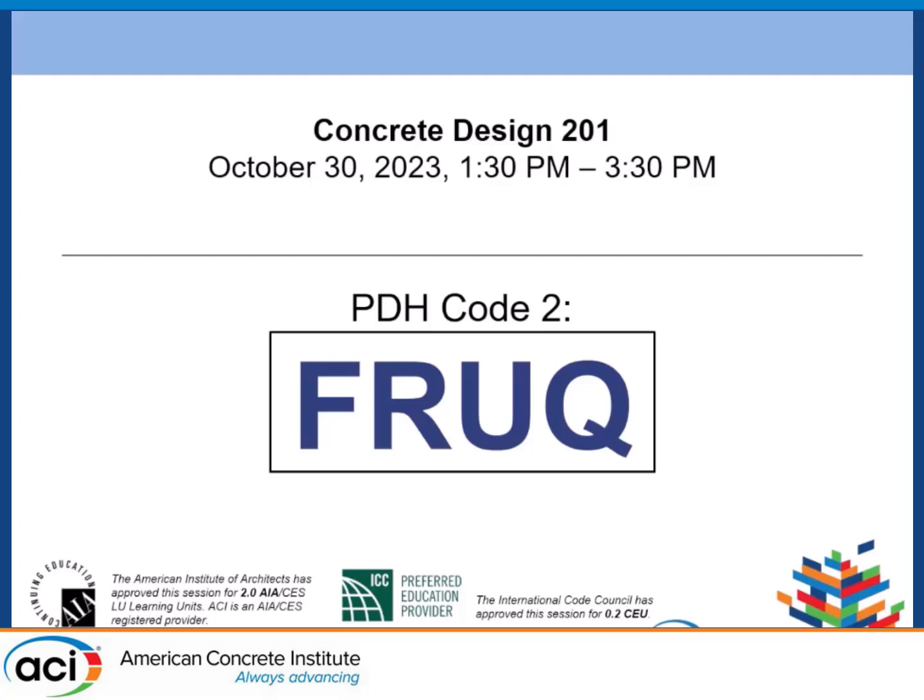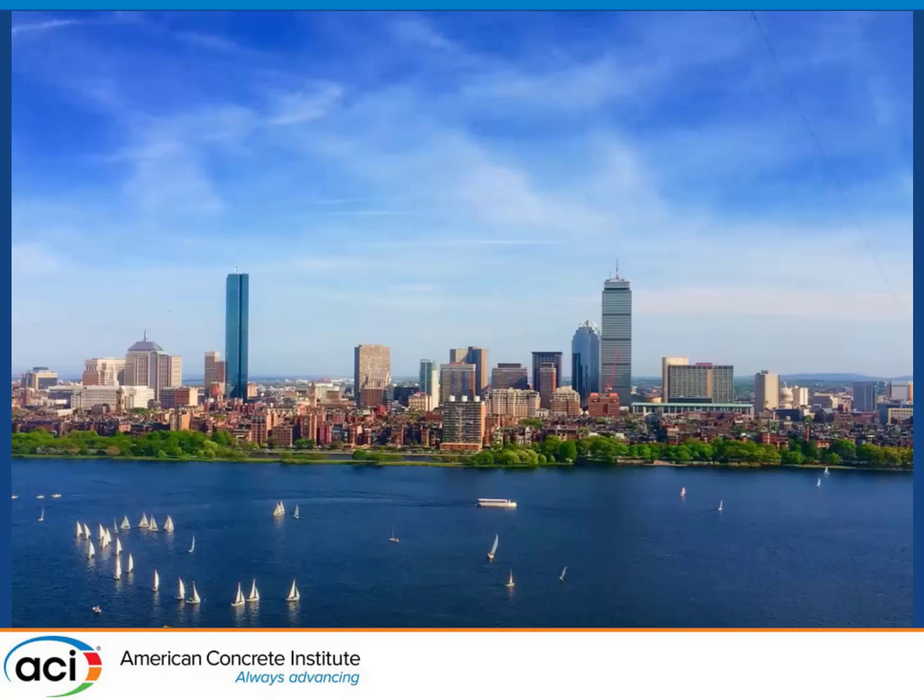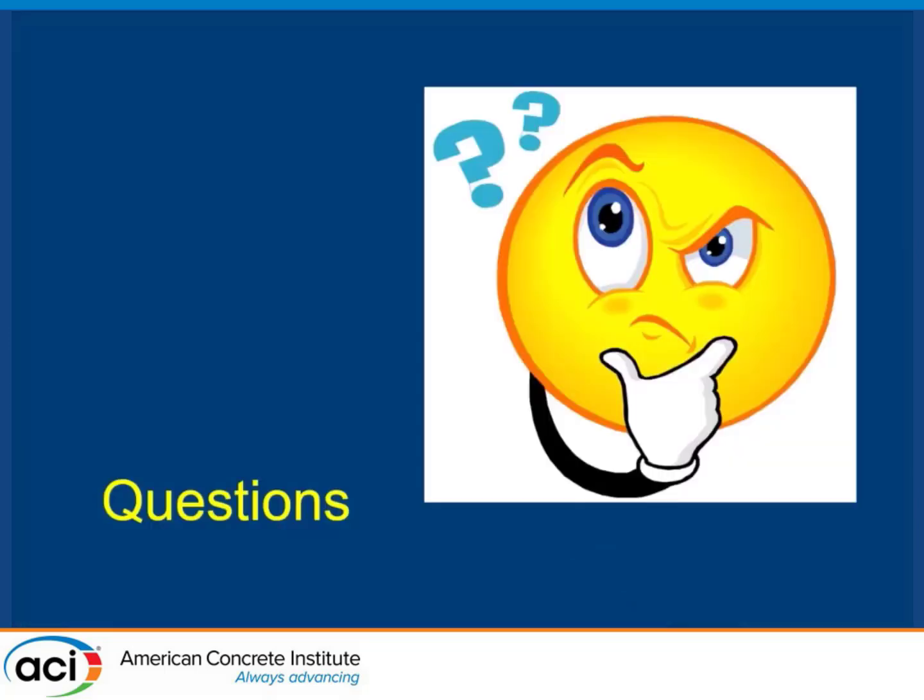Yeah, so, thank you. Yeah, put it down. All right, you go too. Yeah, so the question is how does the interaction occur? And what we're going to get into is, for the same anchor group, you do have tension, you do have shear. We have an interaction equation that you use. You take the value that you calculated for tension and the one for shear, you combine them by a certain equation, and that tells you the capacity of the breakout.